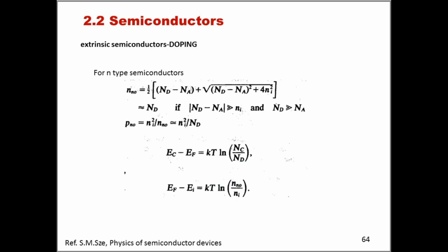And as we anticipated a couple of slides ago, if we consider an n-type semiconductor, the total density of electrons is simply effectively the number of donor dopants, while the density of holes in this n-type semiconductor is simply given using the mass action law, ni squared over Nd.